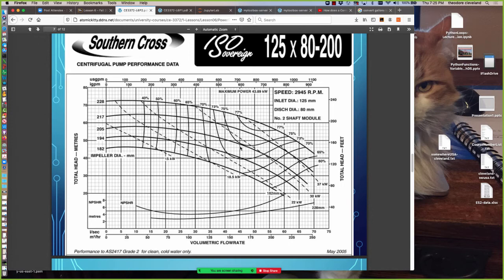So the sweet spot for this particular pump is right in this region here in terms of efficiency. We're at 70% and greater efficiency when we're in this region right here, where the cursor is circling around. And right here kind of is dumb on a video, so I've got to assume that you can see my cursor moving.